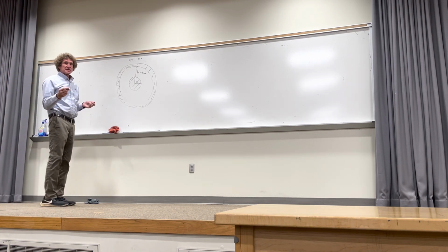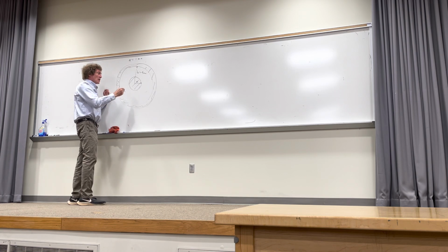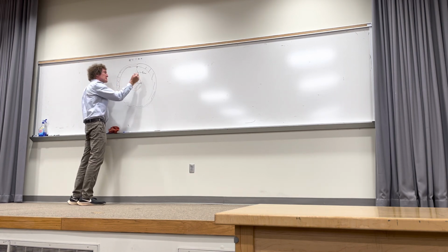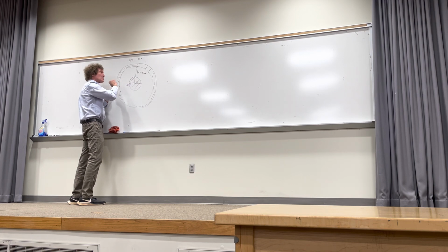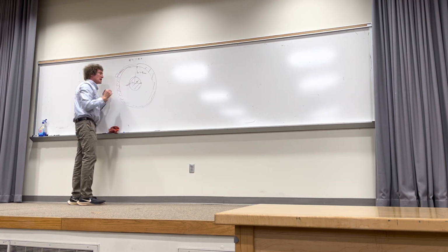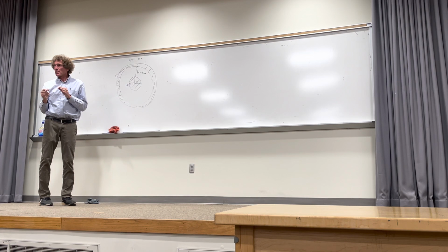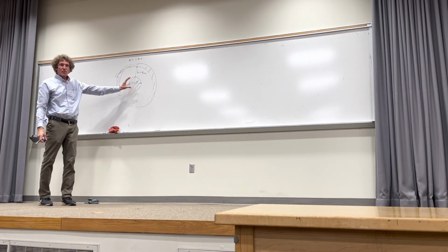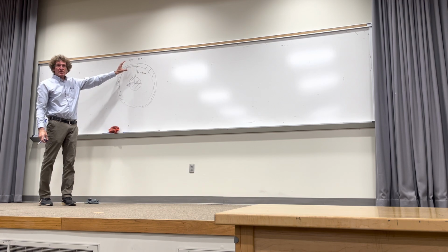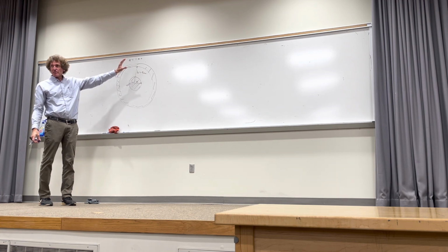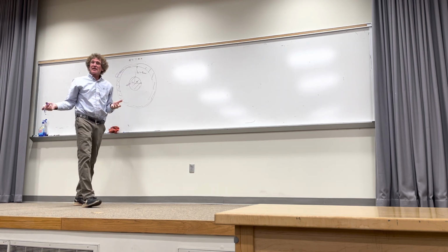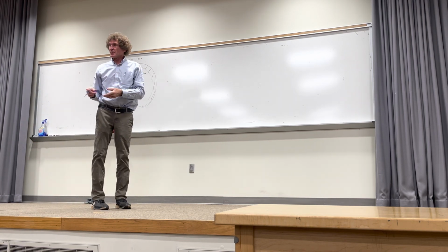So the idea is this. This is a transmission line, so current could be going down the central core and returning in the outer sheet. Y'all follow me on that? So you need to calculate the resistance per meter of the inner core and add that to the resistance per meter of the outer core. Y'all follow the idea? All right. For the inner core, the resistance per meter is going to be the same as what we just did in terms of the actual matter-of-fact calculation.